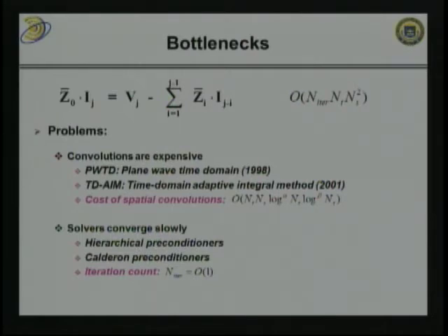Okay. Now, secondly, suppose that you have computed all these things rapidly. Suppose that you have computed the right-hand side rapidly. Now you still have to solve the matrix equation on the left-hand side. Okay. Turns out that is also problematic. It is problematic because we typically don't solve these things directly, say using LU decompositions or things like that. No, we solve them iteratively. And it turns out that this matrix equation is often ill-conditioned.